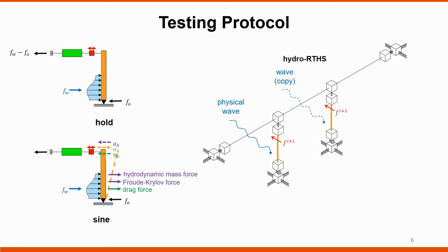And then we looked at a number of different effects. So in an offline way in the numerical model, we could apply some seismic loading and get some damage built into the system before we impact it with the wave loading. And finally, because we could play around with really any aspect of the numerical model, we could look at those hydrodynamic forces, and we could say, oh, well, the wave loading actually has a much higher density because it has sediment in it. And it's picking up all this debris along the way, and so we can play around with the impact of that wave loading in a way that we would never be able to do in our experiment because we have to use clear water.